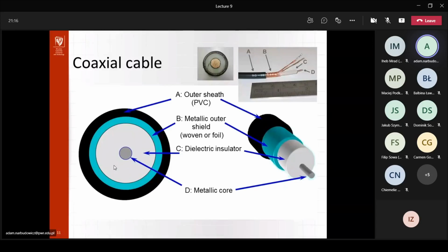However, it may create issues when you try to connect your cable to antennas, simply because with antennas you also have balanced and unbalanced types. We are not going to discuss that within this lecture, but in general, when you connect an unbalanced cable like this one to a balanced antenna, like the dipole we saw a few lectures ago, which simply consists of two symmetric wires, you need a structure which is called a balun.